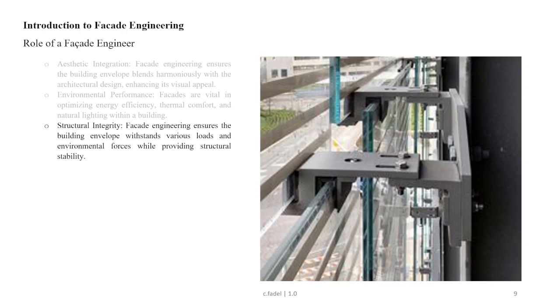Last thing is the environmental forces. What are these? These are various environmental forces that affect the building envelopes. It includes temperature fluctuation, moisture, and ultraviolet radiation. So therefore the engineer should consider these factors in the facade materials and design, and appropriately include protective measures to ensure long-term durability and structural stability. This may involve incorporating insulation, for example, or moisture barriers, UV resistant coating, or a weatherproofing system to protect the facade components.